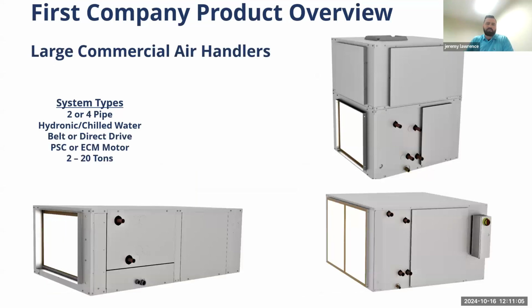Large commercial air handlers. This is where First Company does the most amount of business inside the GTA, and where all of the vertical fan coil manufacturers are willing to go direct, from developer or manufacturer straight to developer. Those amenity spaces, the lobby, the gym, the conference centers. This is where First Company really shines. Customized 2-4 pipe air handlers in high vertical or horizontal configurations, ECM motors, 2 up to 20 tons. So these systems are customizable by the factory to exactly what your requirements would be.